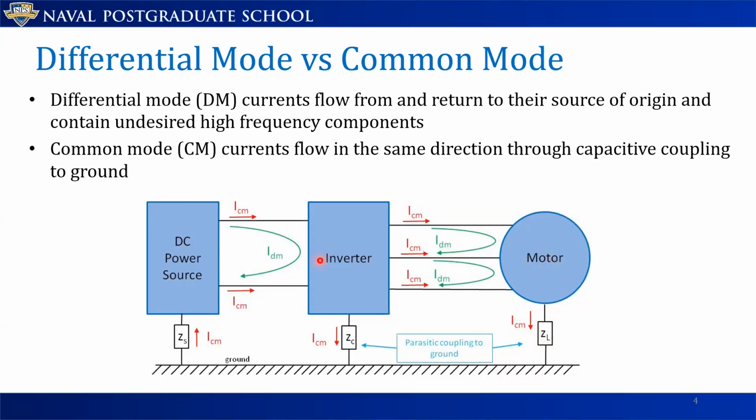So these will not circulate at low frequency, such as 60 Hertz or 100 Hertz, but they will circulate at the switching frequency of the inverter. And this, of course, is because the impedance of a capacitor is inversely proportional to the frequency, right? So this will become more and more like a short circuit as the frequency goes up.